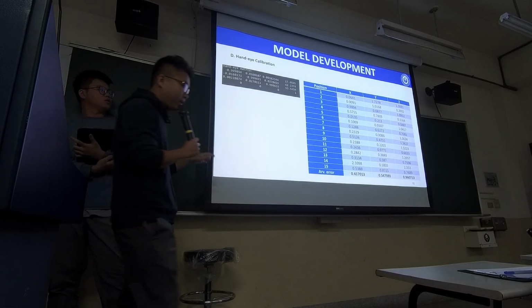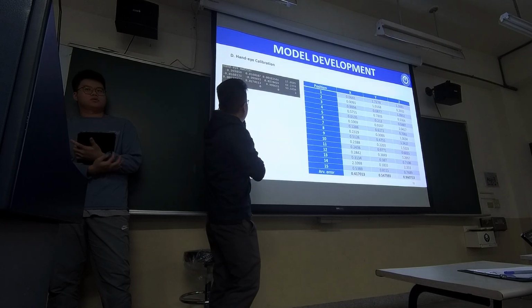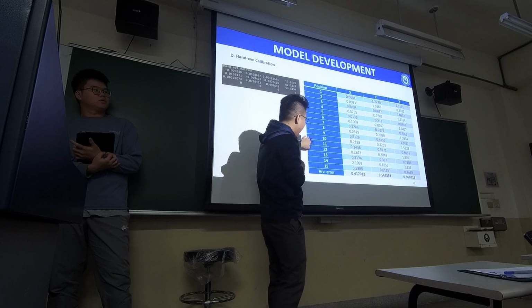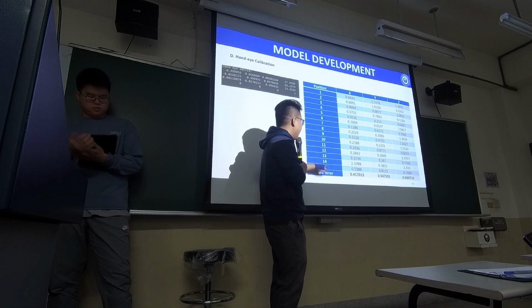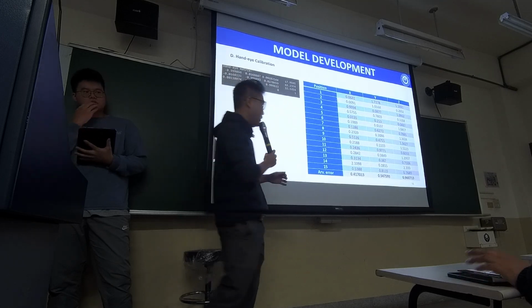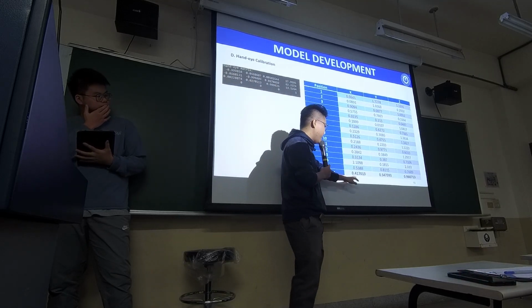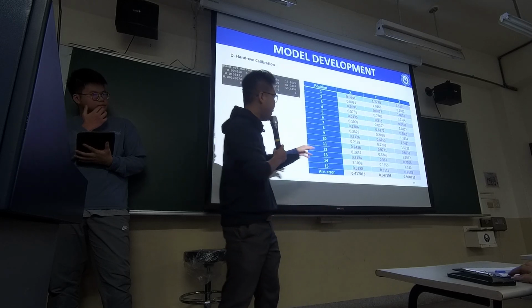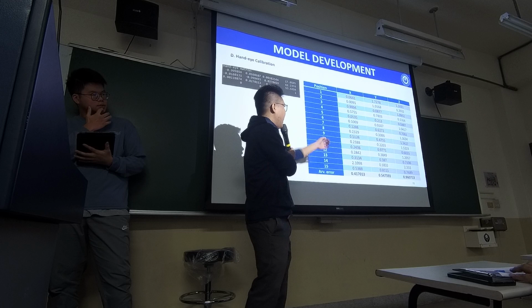After calibration, you get the hand-eye matrix like this, and I took 50 positions from the checkerboard, and you can see the error. The average error is less than 1 millimeter for each axis.